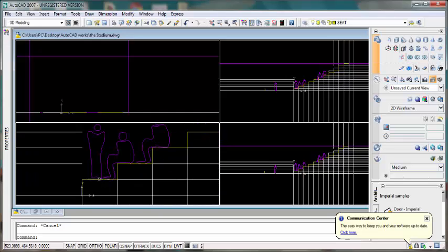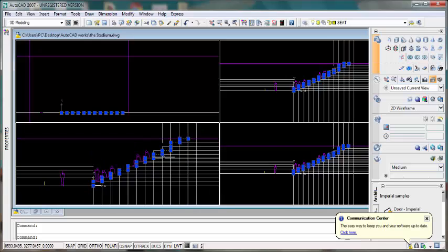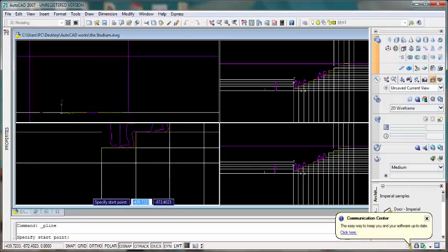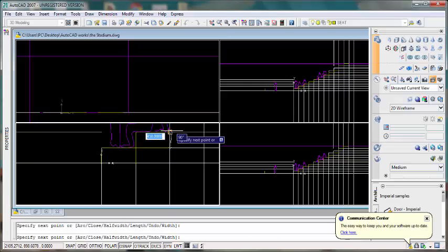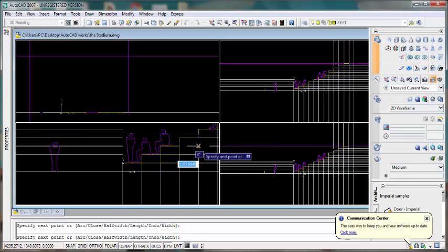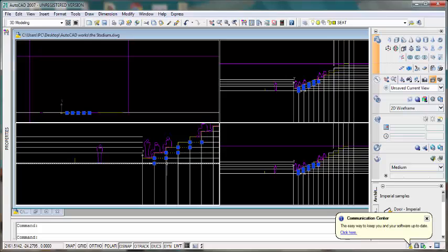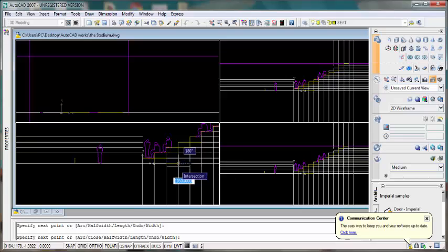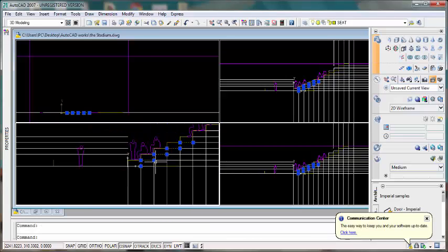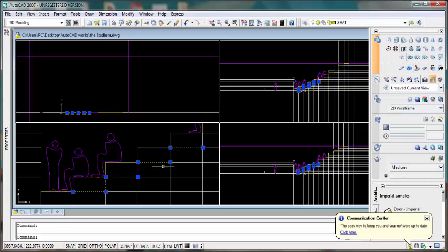I have just created a polyline of this step, which is what you are looking at. To create a polyline, you come to the draw tab, pick polyline, and you can start. Let's say from here, you move like this, keep moving like this, taking note of the directions. Of course, you are the one that knows exactly what you want to do. When you are done with that, you can easily remove your construction lines that you used as guide, and you're now ready to go. So this is just a demonstration of how I created this polyline.